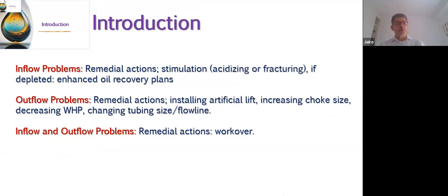Inflow problems: inflow is defined as the performance from the reservoir to the wellbore. Remedial actions are stimulations, either acid or fracturing, depletion, and enhanced oil recovery plans. Outflow performance is the tubing.